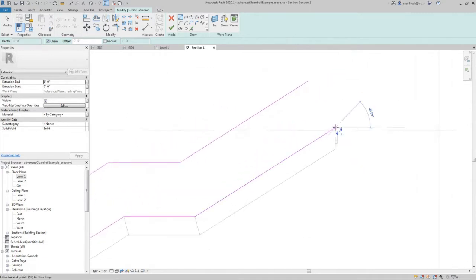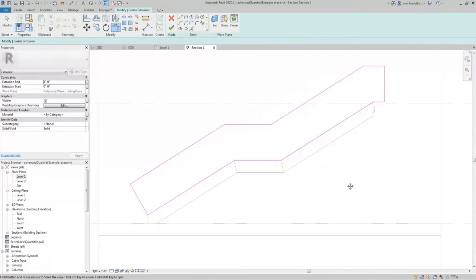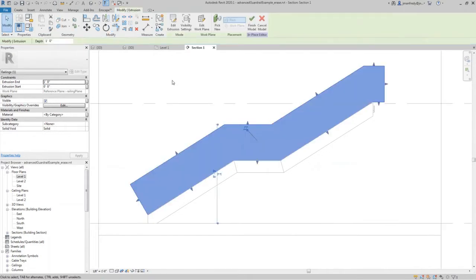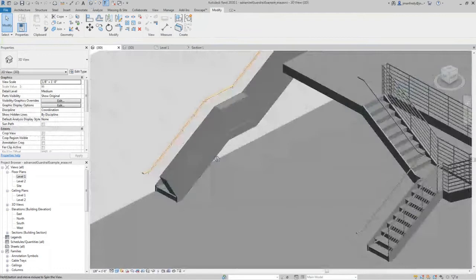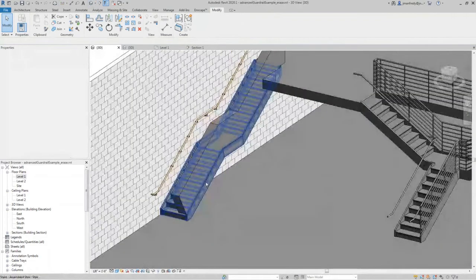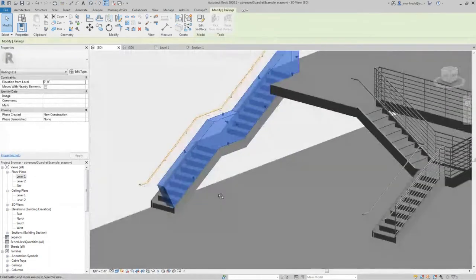And maybe the top one is going to go this way and up. And perhaps I offset it 3 feet as well, whatever dimension you're after, and I trim these pieces. So there, I want the railing to follow this shape, but it's a wall. So when I accept it, and I accept it here, I've built a 3D model right there of a wall.